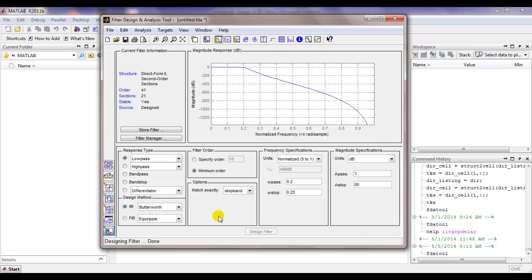Okay. As you see that it may not look as, for example, good as the FIR filter picture that you saw earlier till you realize the scale on the y-axis. Okay, just this one block is minus 200 dBs. You are significantly attenuating this. This is like minus 1300 dBs.